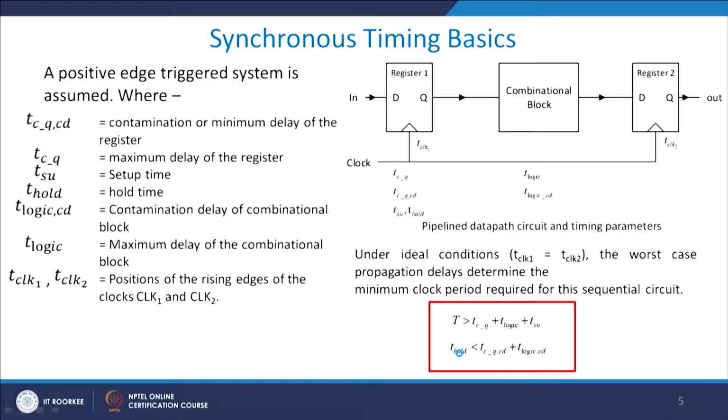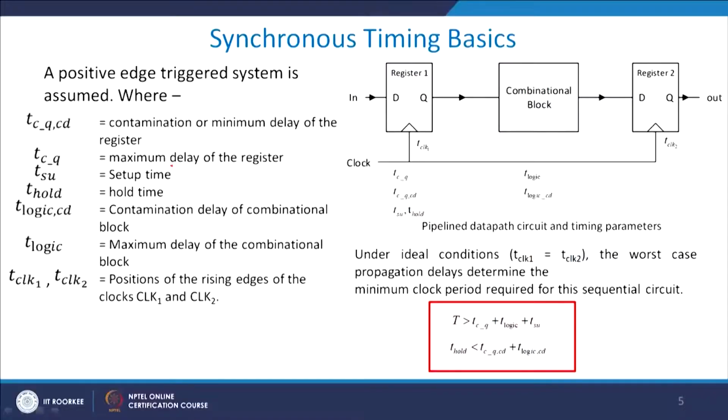Now, let me come to the basic timing analysis. We have already done this in our previous class, but I would still like to give you an insight into it once again. So, the first delay which you see is the setup and hold time, very simple. Setup time is defined as the time before the rising edge of the clock when the data should be held stable, so that the input register is able to properly accept the data.